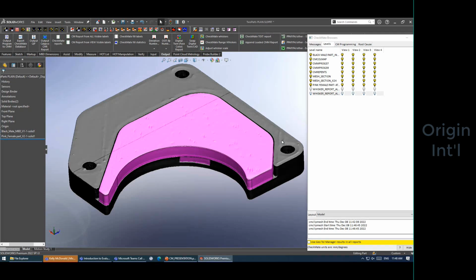Where scanners have really taken off is as the mesh sizing in scanners gets smaller. You're pushing 12 megapixels on a 50 by 50 millimeter area now. As you get into small medical devices and things that you traditionally used gauges for or small scale CMMs to take minimal data sets, the smaller the geometry gets, that's where what we call metrology grade scanners are really helping people understand their parts better.